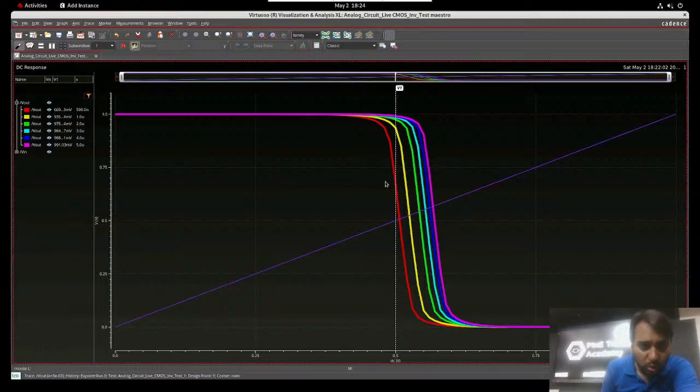You want to decrease the output towards the left side, but the output is shifting towards the right side. So you can reduce the width of the PMOS, to less than 0.5 micro, because higher width gives a higher voltage on V out. So find it from 500 nano. At 500 nano the voltage is 669.